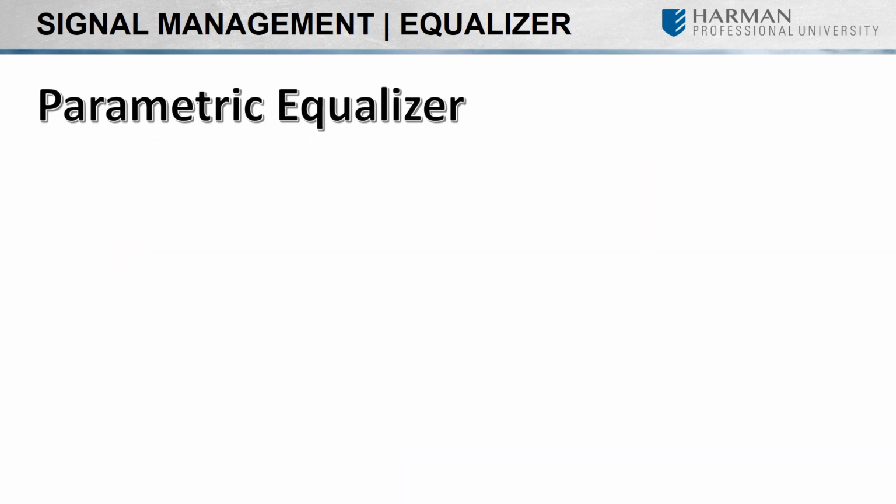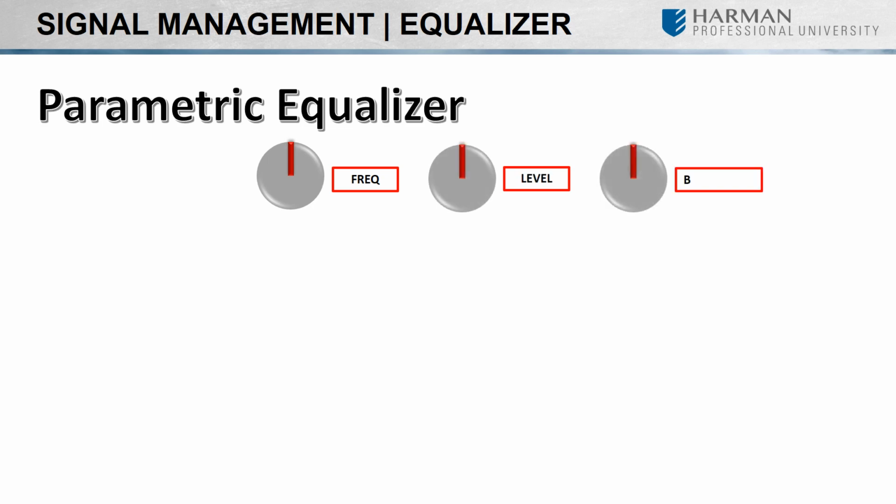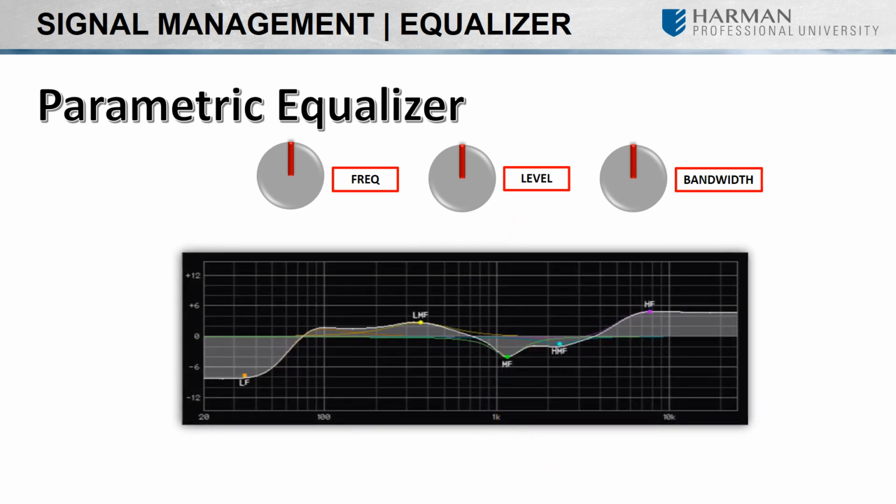Parametric EQs earn their name through allowing the user to adjust multiple parameters, unlike graphic EQs which adjust frequencies that are a fixed width. A parametric EQ can control three aspects of each frequency: the center frequency, or the frequency that's being selected to adjust, the level, boosting or cutting, turning up or turning down, and the bandwidth. The bandwidth, also known as Q, can be made extremely wide or extremely narrow. Overall, if you need an audio equalizer, a parametric EQ permits finer adjustments than a graphic EQ.